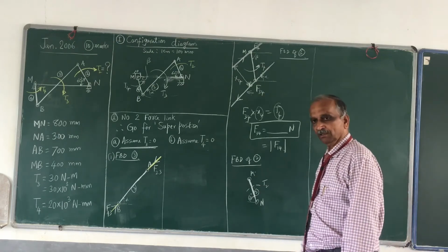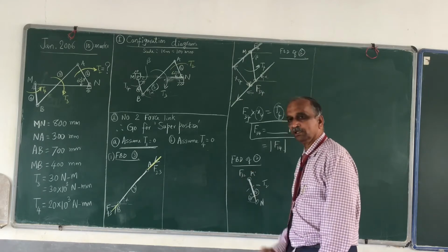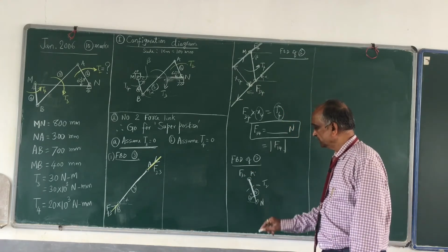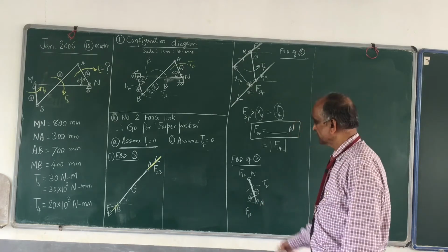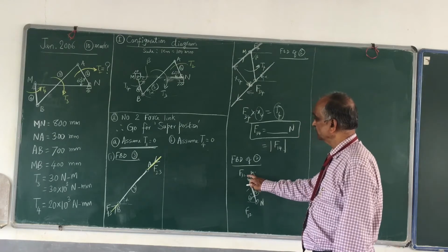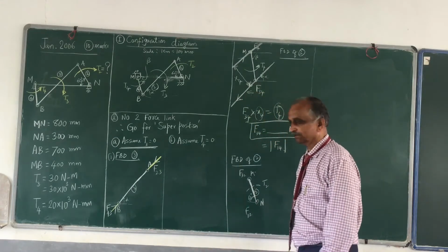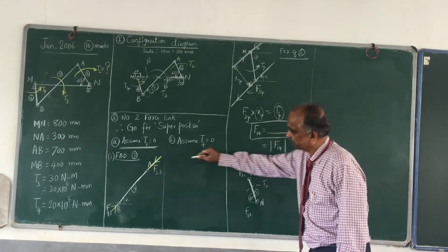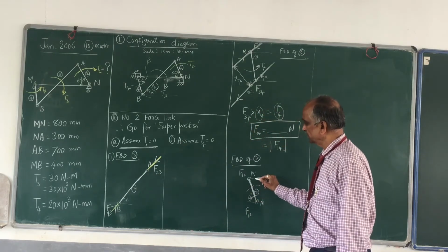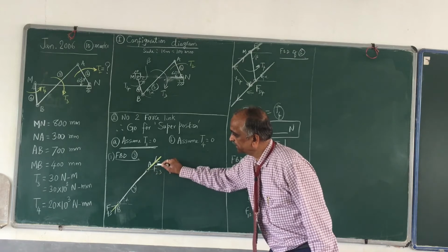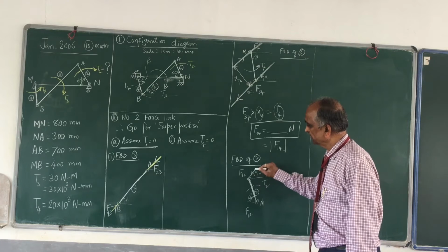So at A, what do you have? You have a force from 3 on 2. At N, you have a force from 1 acting on 2. Any information about F32? Yes, F32 and F23 are related. They have the same line of action. Draw a line parallel to this, at this point. As you know, this angle is the same as alpha. You measure alpha and draw this line.